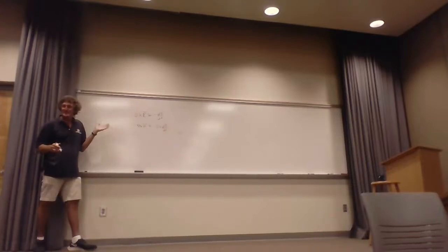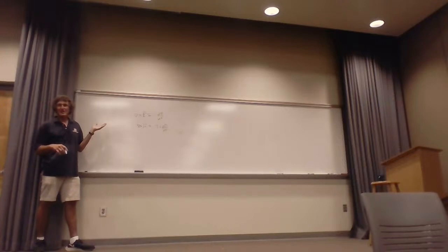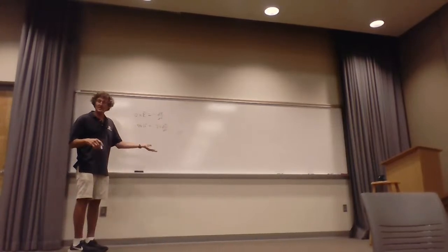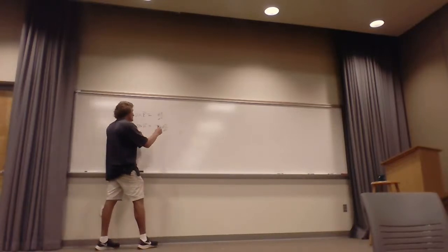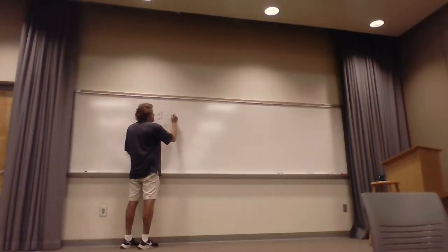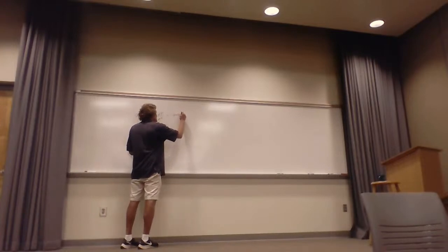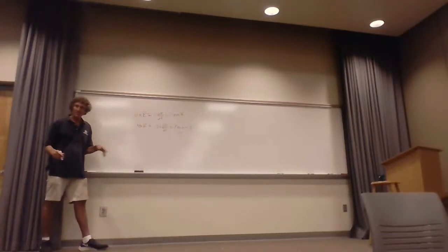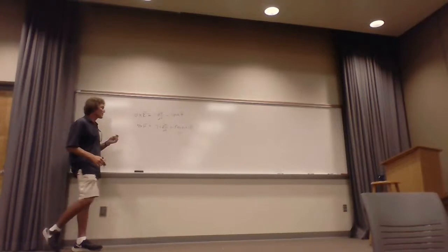Anyway, that's Maxwell's equations. Sort of, they dictate photon behavior, as we know. So from those, we went to the time domain, or frequency domain, right? And then we got one equation. Now, when that happened, this becomes minus j omega mu times H, and this becomes sigma plus j omega epsilon times E. If you remember when we did that, right? Then we turn the crank on this one.